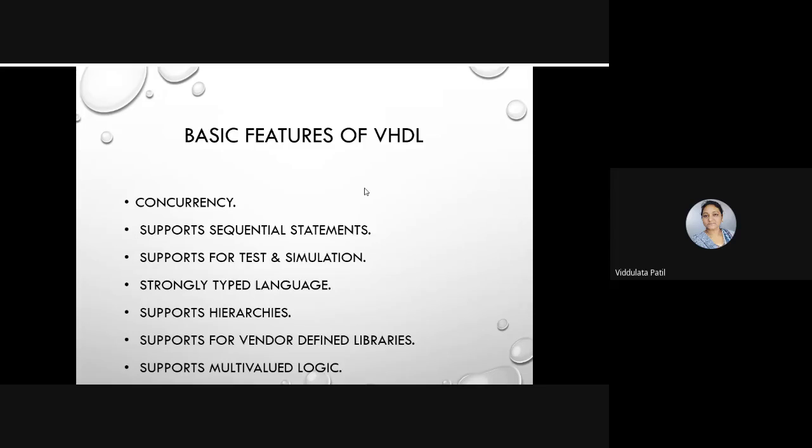Okay. So for that purpose, we need to use a proper data type, or we can say in other words that a correct data type is needed whenever we are writing a VHDL program. Okay. Then it supports hierarchies. Then it supports vendor defined libraries. So there are certain libraries which are inbuilt in VHDL programming, but at the same time, user defined libraries are also supported by VHDL. So that is a very good feature of VHDL programming.